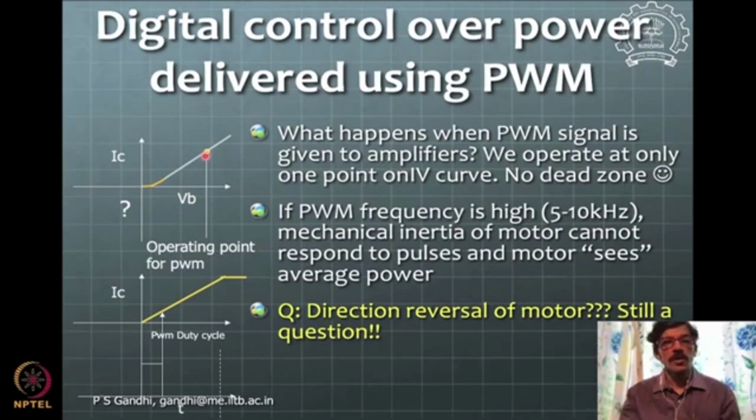the noise, which we said is in the small range here, is not going to bother us anytime now, since we are operating at this point. The noise will be much smaller than this value here. Since the voltage value that we are providing is either 1 or 0, the noise levels are relatively low as compared to that, and that's how we get rid of the noise problem here. And then how do we change the amount of power given to the motor? By changing the on time.